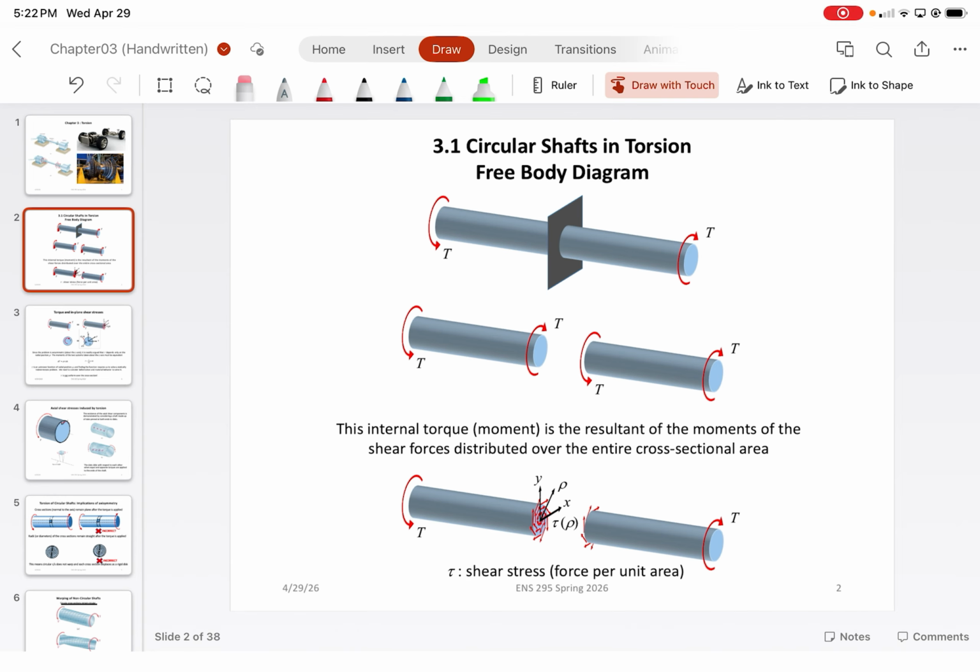Now remember, what is a shear stress? It's a type of stress that occurs on a sliding plane, all right? If you guys remember from when we went over shear stresses at the beginning of the semester, it was always just some type of sliding force, the shear force. For beams, the shear force just determined whether the beam vertically displaced upwards or downwards, and then the bending was a byproduct of that shear force. So the shear force is a type of sliding force. In this case, it's also a sliding force, but in a rotational direction.